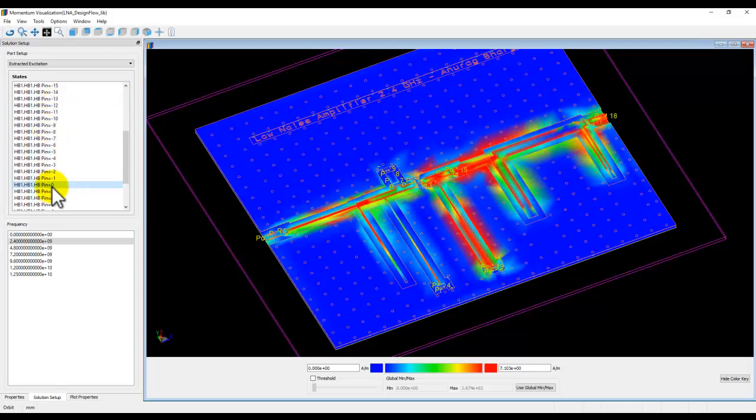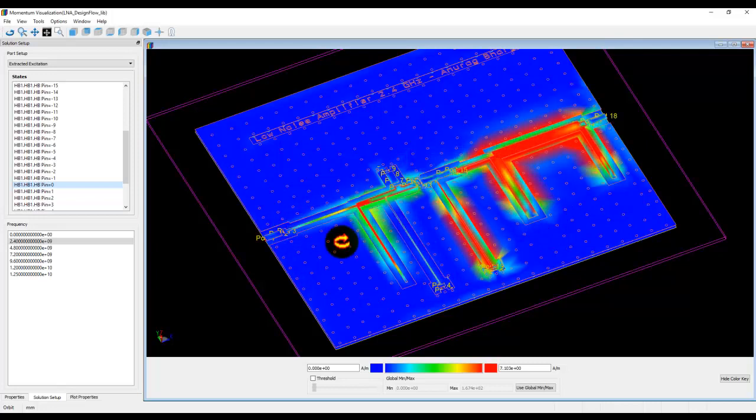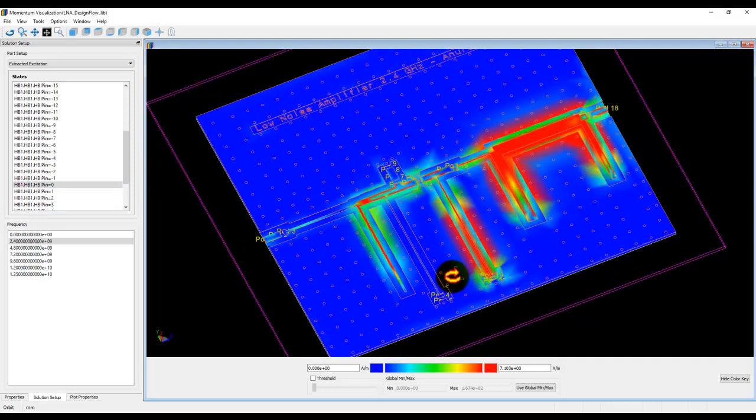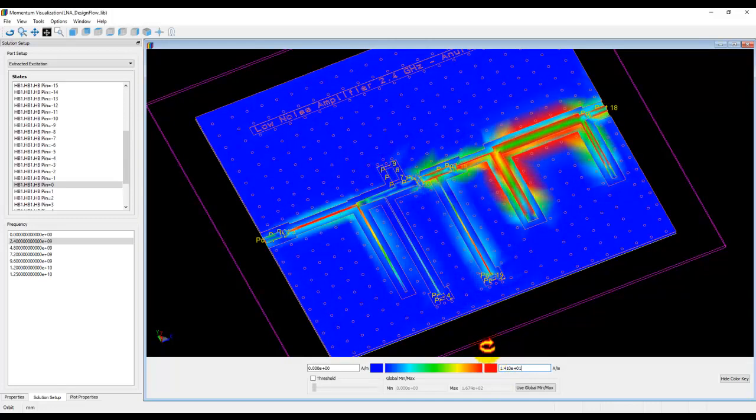Okay, so once we reach the input compression power point, let's say 0 dBm, we can see how the currents are scattered in our structure, and we can see all the current density information. And again, you can change this density level by changing the level here just to keep everything in control. All right, so that was about the fundamental.